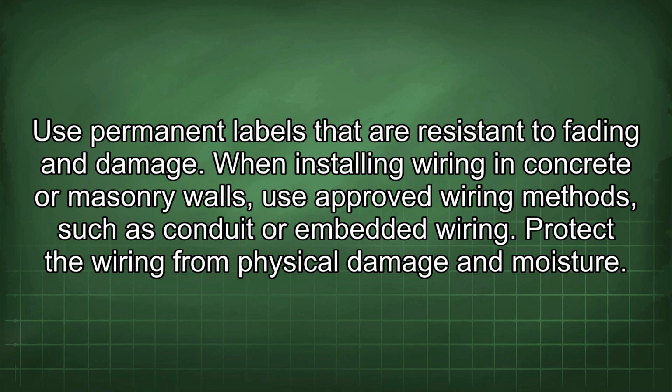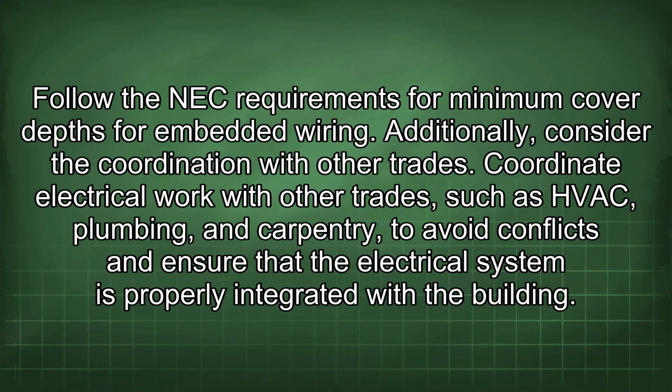When installing wiring in concrete or masonry walls, use approved wiring methods, such as conduit or embedded wiring. Protect the wiring from physical damage and moisture. Follow the NEC requirements for minimum cover depths for embedded wiring.